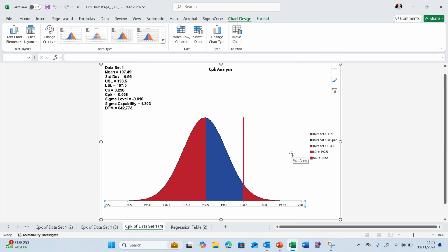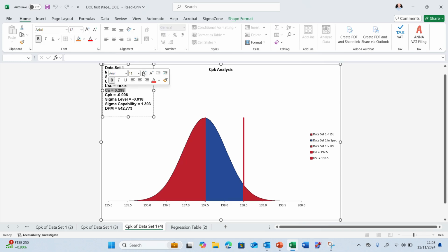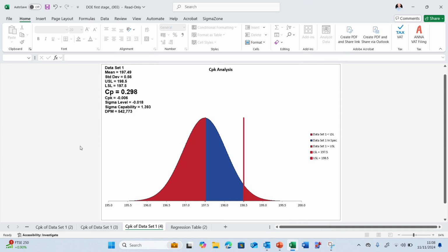Now look what we've done to the CpK by running faster. You know, I know we're off center. We could probably center that. We could ask the optimizer to center that for us. But even if we centered it, look at the CP here. The capability here is only 0.29. So regardless of what we do, we haven't really got a good situation.